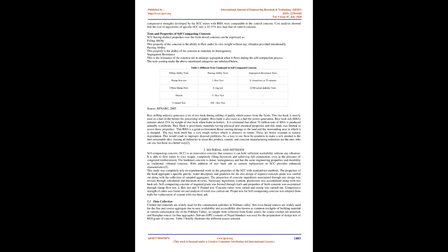Concrete that segregates loses strength and results in honeycombed areas next to the formwork. A well-designed SCC mix does not segregate, has high deformability and excellent stability characteristics. Self-compacting concrete produces resistance to segregation by using mineral fillers or fines and using special admixtures. Self-consolidating concrete is required to flow and fill special forms under its own weight. It shall be flowable enough to pass through highly reinforced areas, and must be able to avoid aggregate segregation. This type of concrete must meet special project requirements in terms of placement and flow.